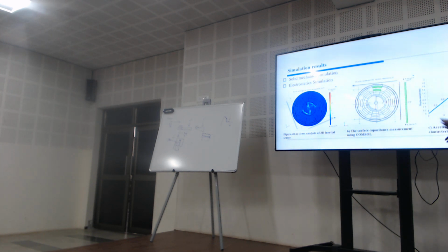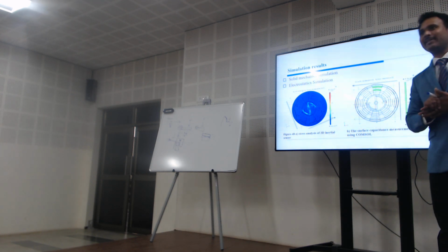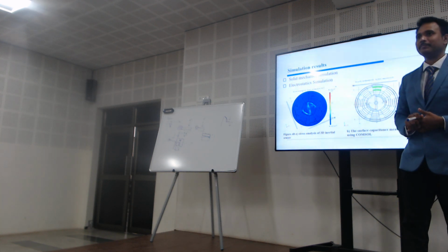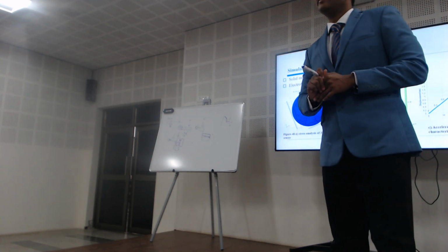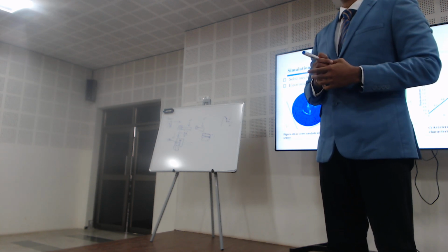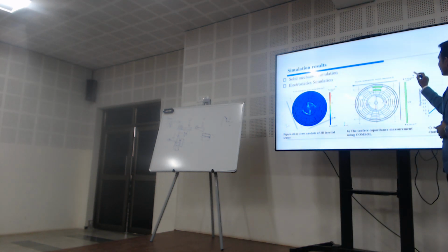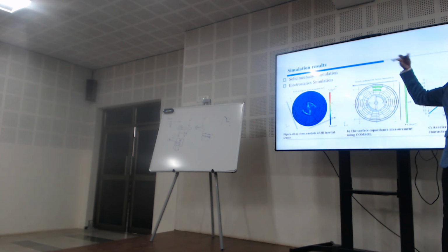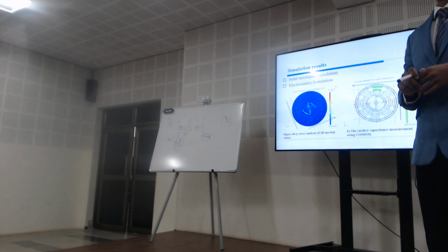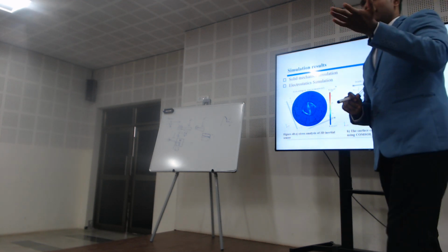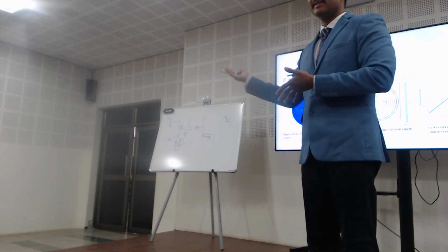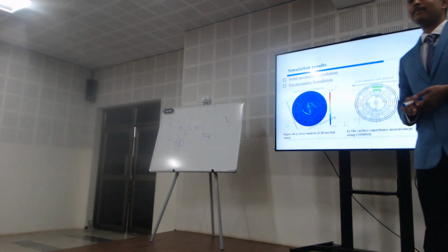Now, why am I explaining this? I got one idea for the design. To increase the sensitivity, I had placed 8 sets of electrodes here. But we are getting a very small value of capacitance from each. Here I can see 8.78 femto, that is 10 to the minus 15, femtofarads, right? That is a very small value. It is not possible to go for electrical analysis. Circuit analysis is not possible with such a small value of capacitance.